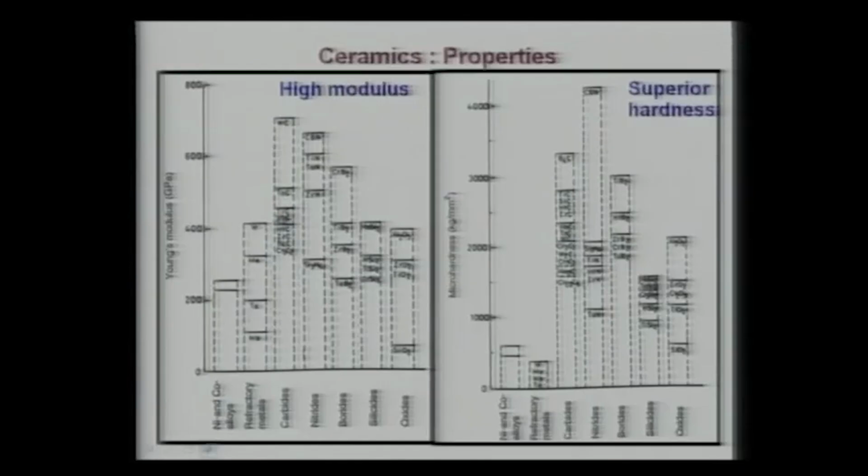Now coming to the modulus, as I said, elastic modulus is important because there should not be much mismatch, and alumina and zirconia have a relatively much higher elastic modulus compared to even steel. So this elastic modulus needs to be tuned before any potential applications can be realized. Now coming to hardness, these ceramics traditionally have very high hardness, more than 10 gigapascal and above, and that is one of the important properties of ceramics which is largely exploited in different applications.